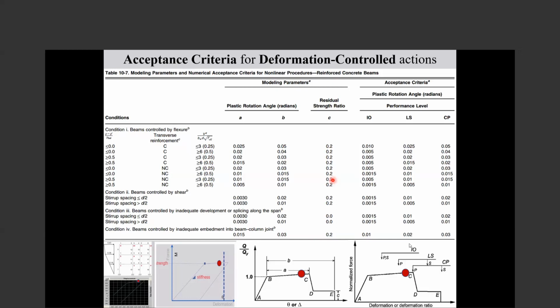We have lots of solutions in the literature, from very well established solutions to include the higher mode effects, the classic work of Chopra and Goel for modal pushover, to the consecutive pushover that seems to be one of the best for taller buildings, and exactly around the same mass ratio that you mentioned is used as a threshold.